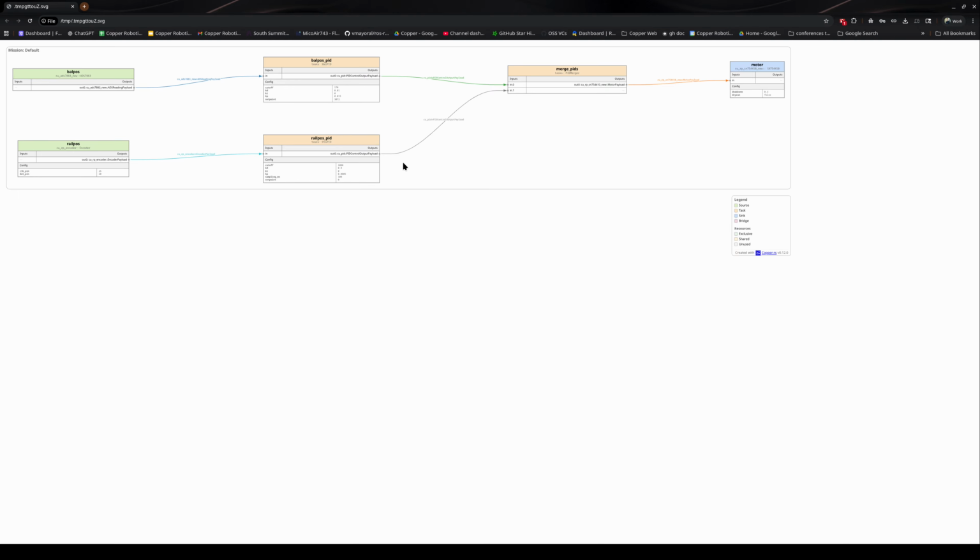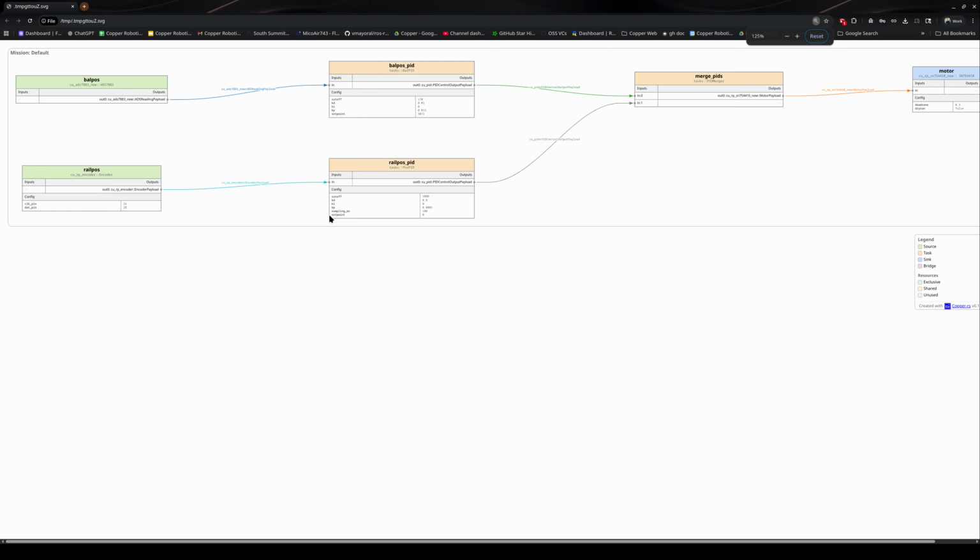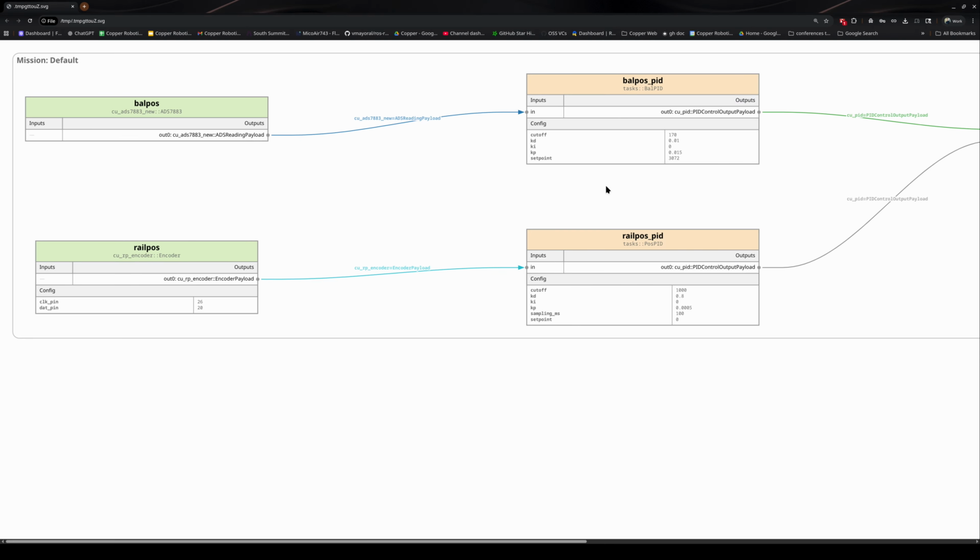You can see in there that that's basically the same thing as what you saw in the real-time environment. But now it's clear what the types are. You have one output that is actually the type of the output. That's a Rust type. Here also you have another one, and you can see that we have configuration, bits of configuration. For example, here that runs on a Raspberry Pi, a standard Linux machine, but we want to put this encoder on specific pins. So we have a config that you can put in the copper config.run.